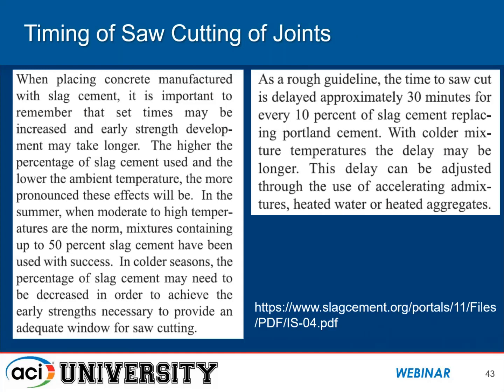In terms of saw cutting, it's similar. There might be a slight delay in saw cutting joints, especially in cold temperatures. And in some cases, they may reduce the amount of slag used at cold temperatures to allow saw cutting within a certain window.